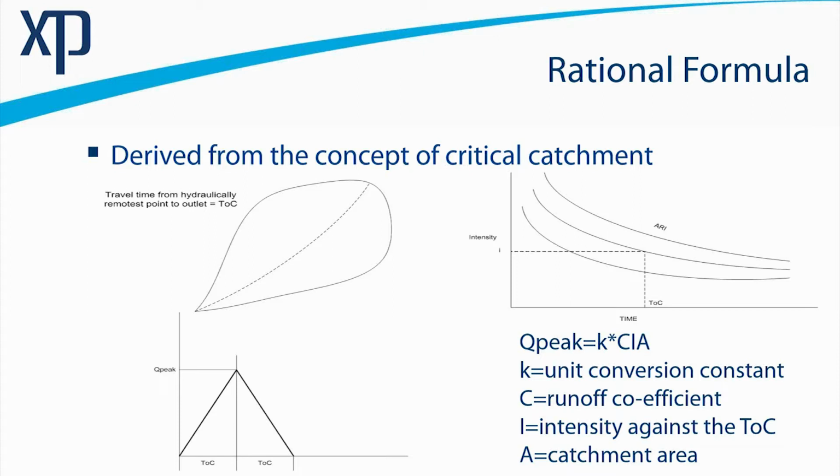How does a river system perform in the real world versus our calculations? Now, you could try and calibrate the rational method to the real world. You could also try and calibrate Laurenson's method to the real world. And your approach would be slightly different in both the examples, but with the ability to get more information out of a hydrology method, which would give you not only just the peak discharge rate in the river system, but also the total volume that contributed behind that peak flow rate.